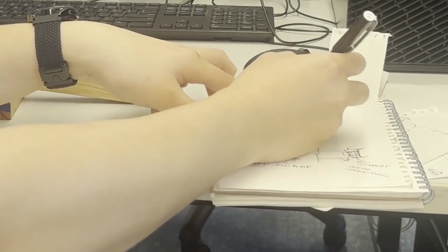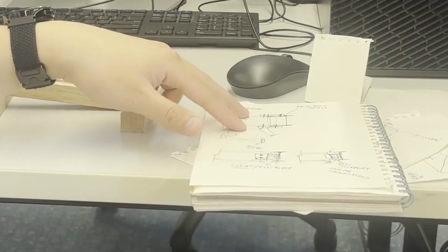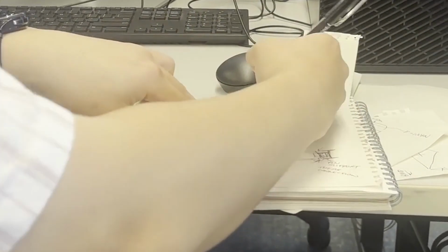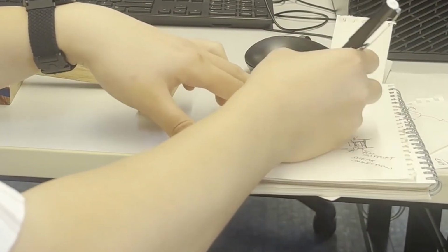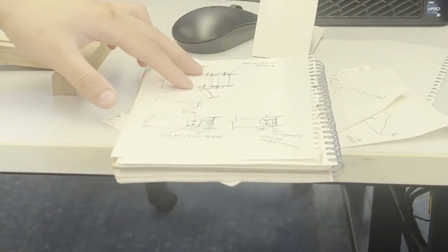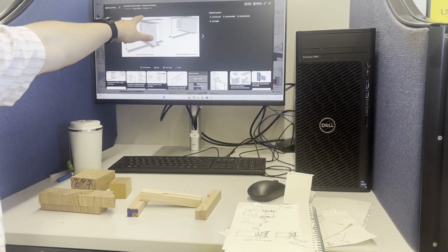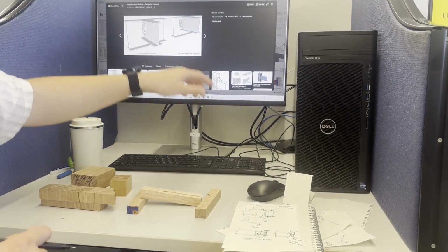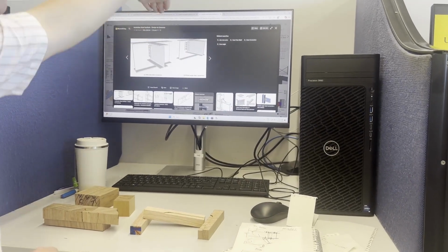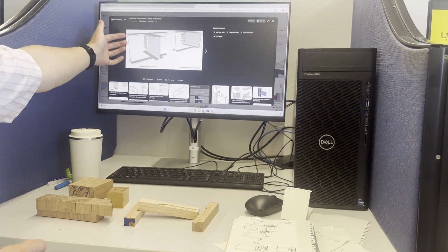So this is pretty typical for something like a splice connection, or something that you do want fixed, because again, as this beam bends, it's going to rotate this other I-beam. So if you do it like this, where you add a plate at the top, it's going to make this connection more rigid, and therefore if this beam does bend, it's going to put this primary beam into torsion, which is not good.